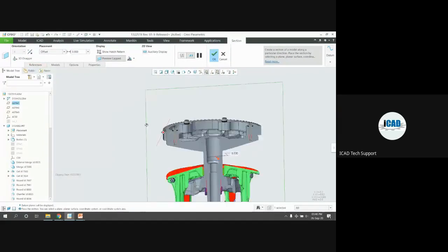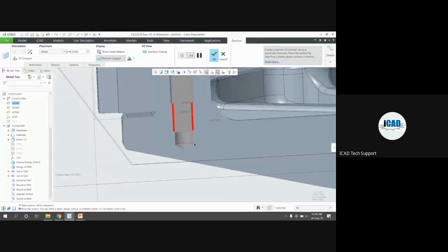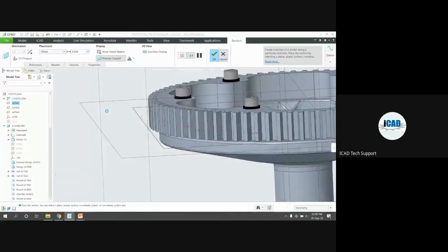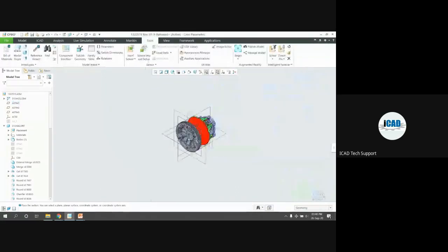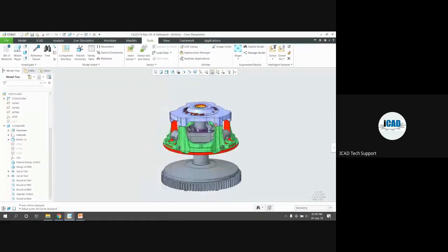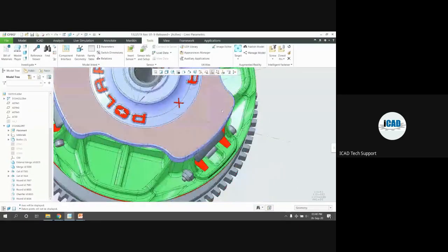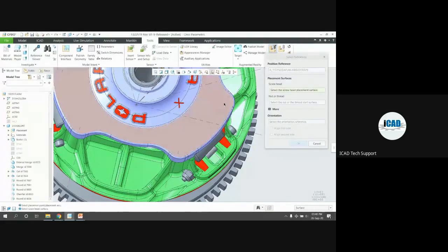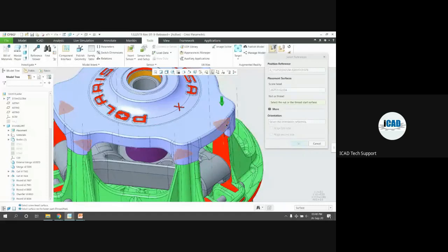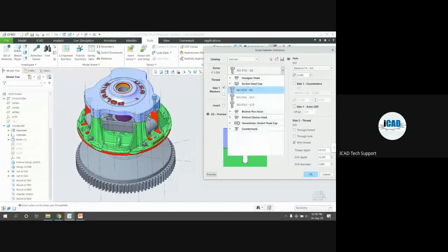Again, I am checking the instance. You can see now the hole will come up to the top portion. I'm just cancelling it. In a similar way, on the top surfaces also you can give the reference for it. Here the references are available. Just insert the screw, select the top surface and select the bottom surface. Here one bottom surface is available. Click on OK. Now again, here is the lock.